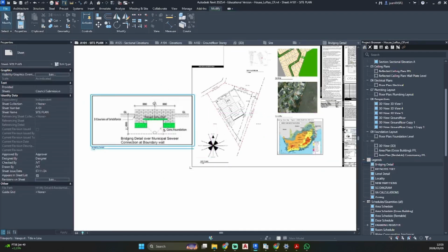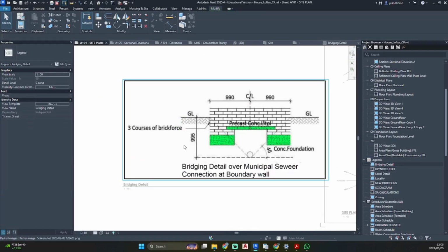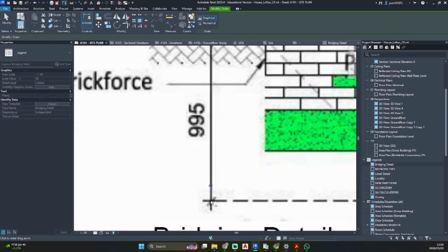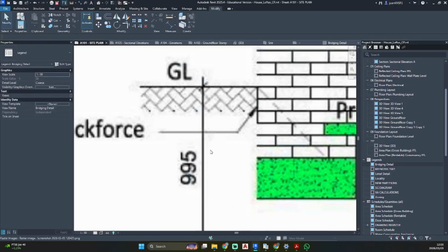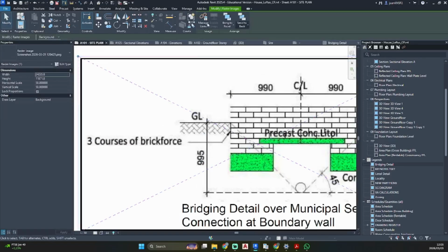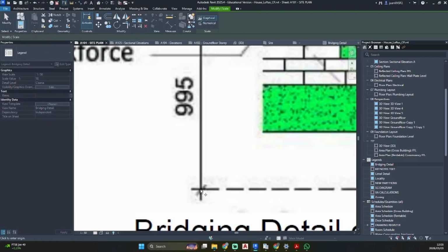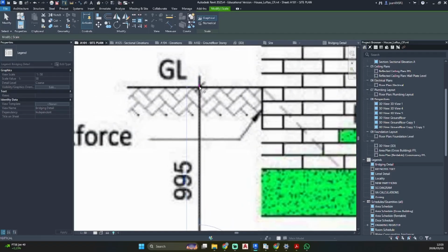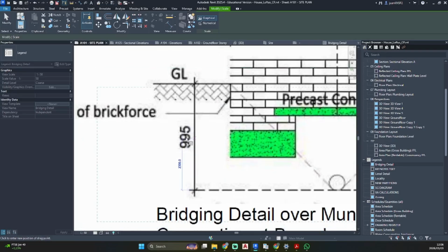So this is very big at this stage. So it's 1 to 50. Now I'm just going to scale this so that this is also in proportion. So I'm going to select my image, go to my top ribbon, select scale, and I'm going to select right about here, go there. We know this needs to be 995, so I'm going to enter 995.